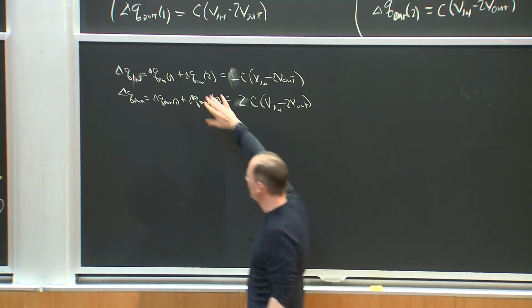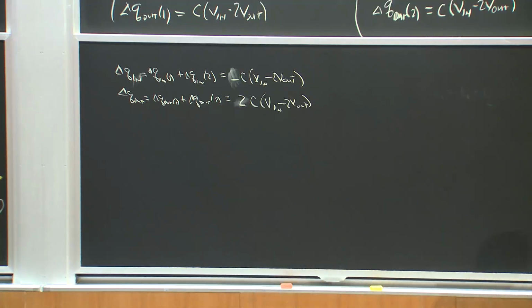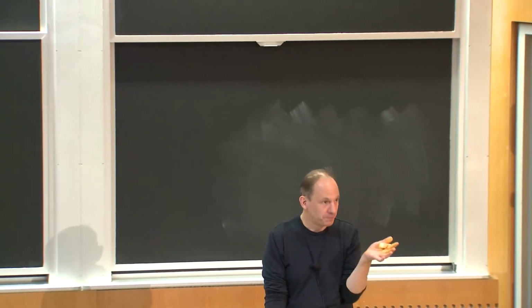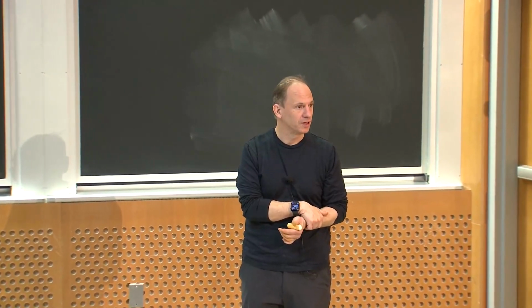Okay, so we have our input and output net charge. If I wanted to talk about the average current going into the input or the output, averaged over a cycle, really it's the charge divided by the period, or equivalently the charge times the switching frequency, right?